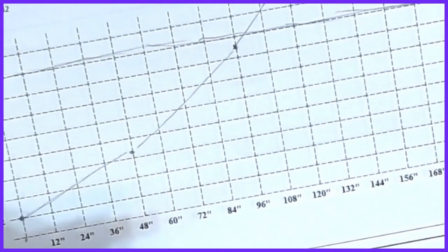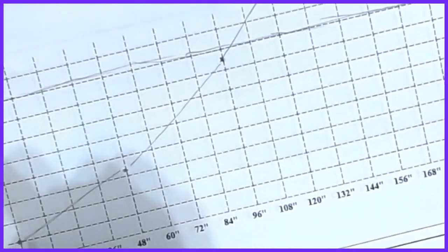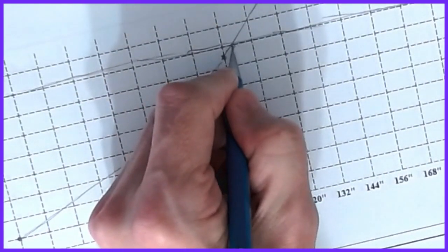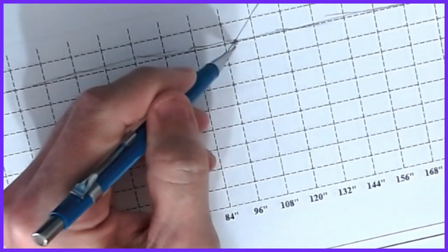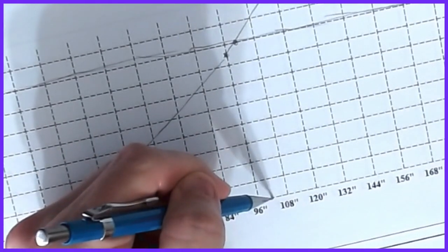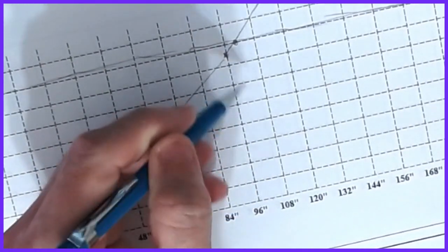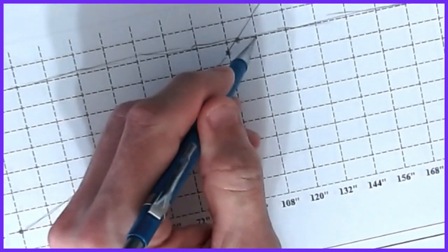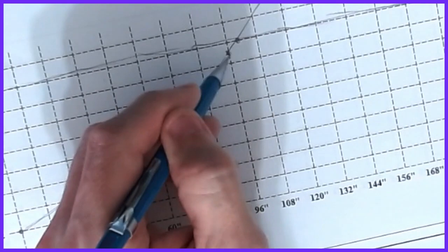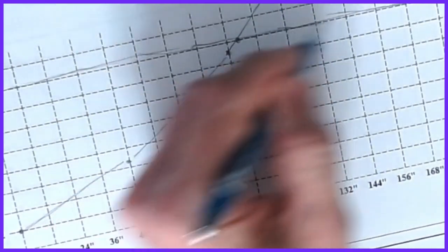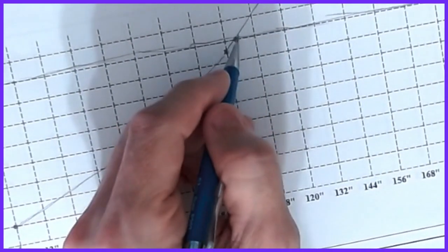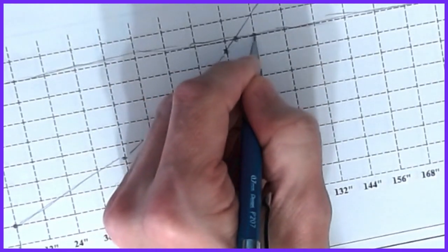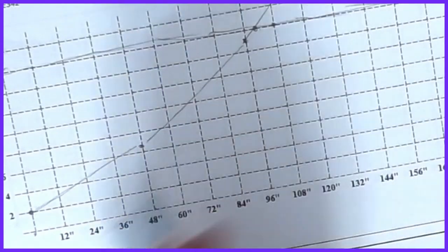All we're trying to do is come up with lines that make decent arrangements of stirrups on this. If you draw this to scale, you can read off that starting at 96 inches, I was at 15, and then at 108, clearly we're at 16, where the maximum controls. Somewhere between 96 and 108, this can start to proceed off of the S max. So this is that third point. A lot of times I'll say, starting at 108, we'll make everything 16, and then we'll build our lines.